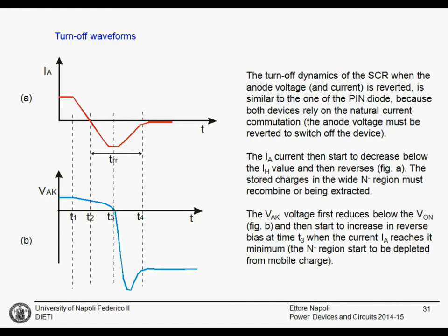Here you just see this short, like from an electrical point of view. In a real device, the problem when you decide to use anode or cathode shorts, the problem is in these large area devices, how many cathode shorts do I use? Which is the area of each cathode short? How far one from the other? Is it better to use more small cathode shorts, or a big one? Everything is a layout problem in the end, and it is really difficult to optimize in this case.